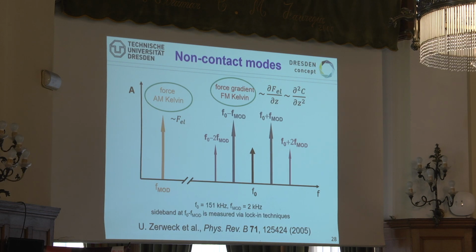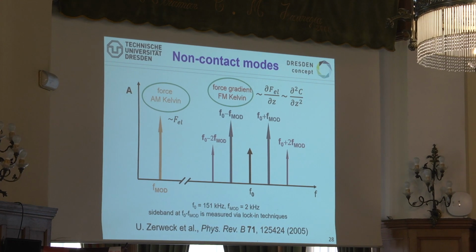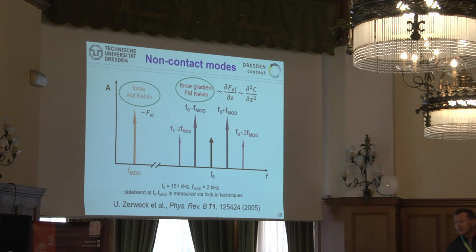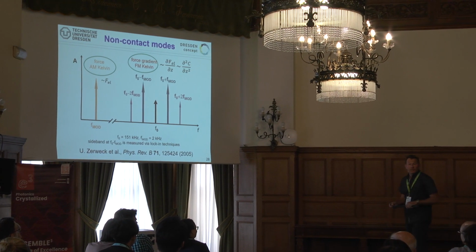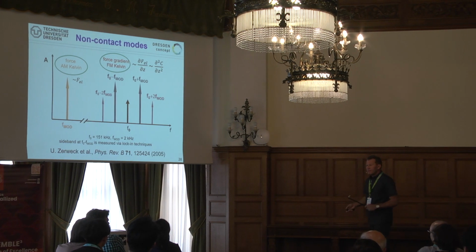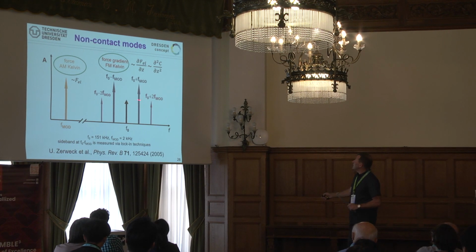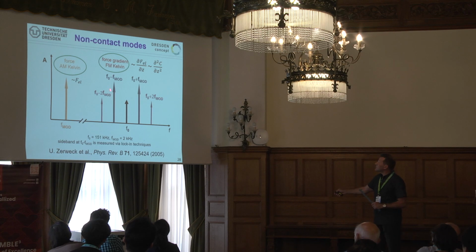We take a cantilever, and you have a capacitance, and we're going to make a derivative of this capacitance. Well, the first order is basically that we have a cantilever, and everything is contributing. If I take this derivative, this means the strongest curvature is contributing only, right? And the strongest curvature is my tip, which means I can balance off everything which is background. So for free, not doing anything. I don't need to manufacture. I don't need a FIB for that. I just need to make the right measurements. And hence, we can really measure fantastically. I want to convince you on that.